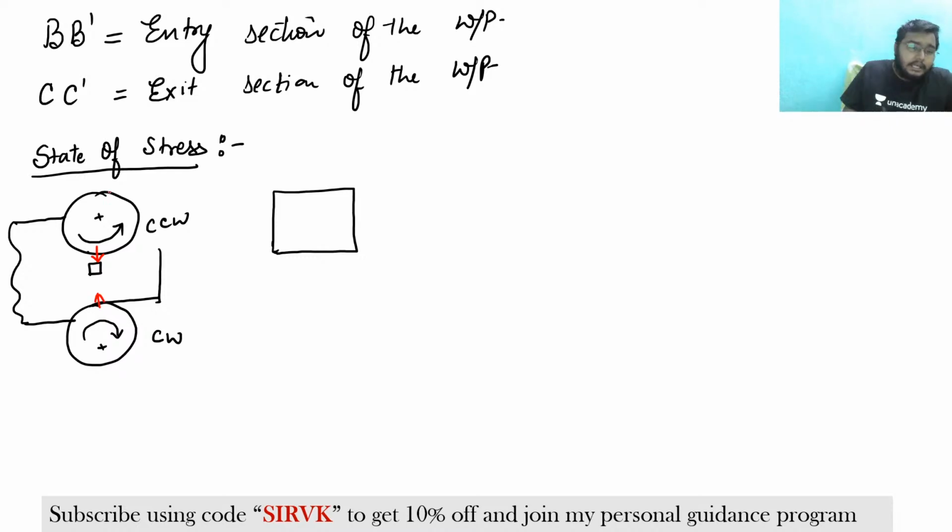Now understand, this roller is moving in this direction, so a shear force would be acting in this direction, and again this roller is moving in this direction, so due to the slip, a shear force would be acting in this direction. So you have the state of stress: a compressive force acting in this direction, and a shear force acting in this direction.